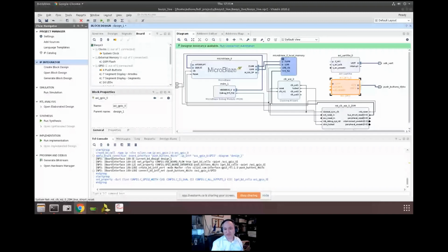Now, that high-level synthesis block is actually written in C and synthesized into RTL, and we'll take a look at that in the next lab. But that's the element of the design that's going to be doing a lot of the drawing on the window. When you output this externally, it will be this HLS block that's running a lot of the drawing. What the MicroBlaze is going to be doing is calculating the positions of the ball and the positions of the bat, and updating this HLS block as to where that data is.